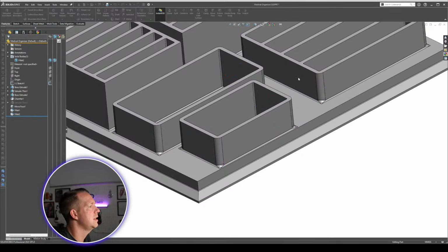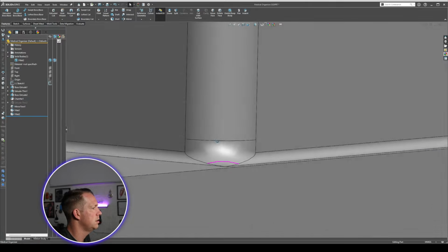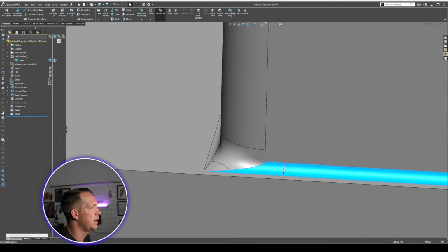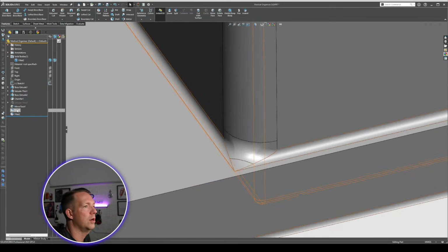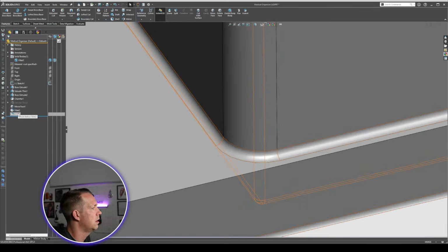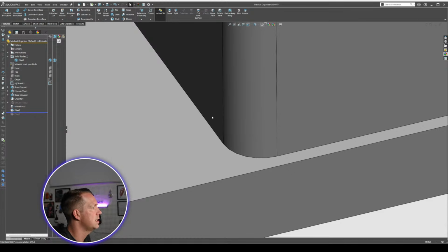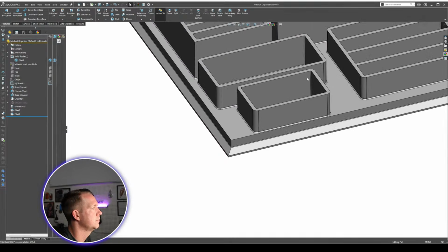All right, now I'll just do those 3 as an example because I'm going to change something here, and what I'm going to change is the order of the fillets. You can see how we get this kind of small fillet here and this large one here. We can fix that by reordering these fillet selections. So I'm going to grab this one here, drag it down. And now we get a nice round fillet because fillet number 2 has done its work before the fillet number 1 selection.